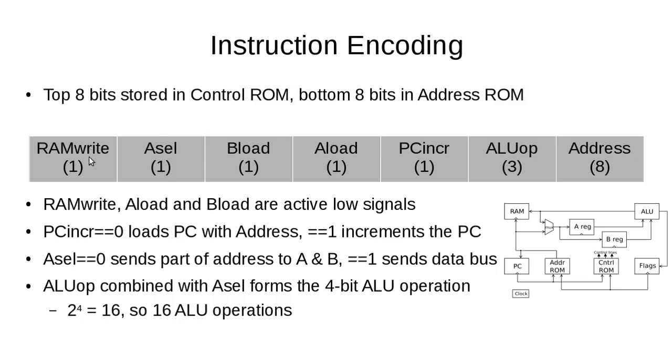Okay, so we've got 2 more control lines. PC increments: if it's a low value, the number 0, then it will actually load the address value to jump to a new program counter value. But typically it's going to always be the number 1, and when the program PC increment line is 1, we'll just simply move up to the next program counter value.